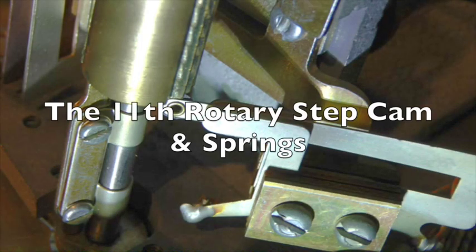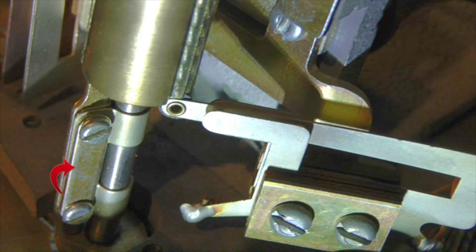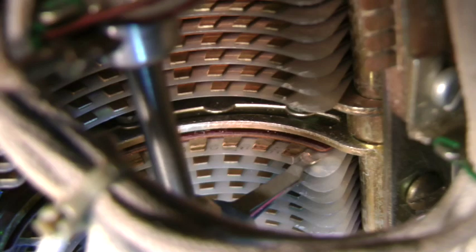Below the rotary ratchet is this vertically mounted cam called the 11th rotary step cam. This is utilized when there is a trouble condition in which the line finder cannot detect the location of the calling line, or when a CO technician is performing a line finder start chain test. In such cases, the wipers are rotated past the 10th terminal on a bank level to an 11th rotary step position where there are no terminals.